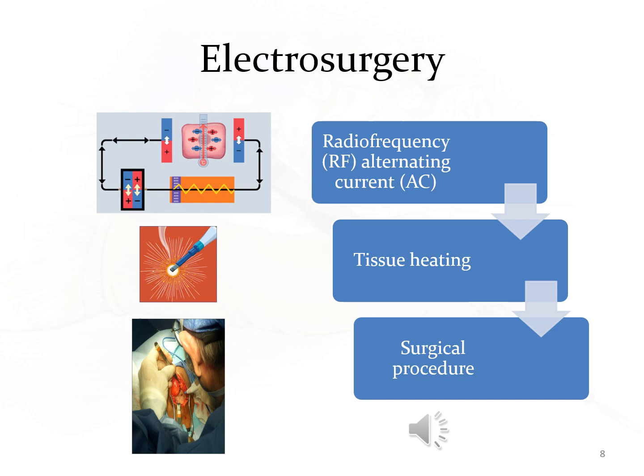Electrosurgical units, ESU, use alternating current and increase the input frequencies from around 50 Hz to more than 500,000 Hz to decrease the chance of muscle and nerve stimulation, which could occur at frequencies below 100,000 Hz. When the electrical current meets resistance, heat is generated within tissues. This leads to cutting, fulguration, desiccation, or another surgical procedure.